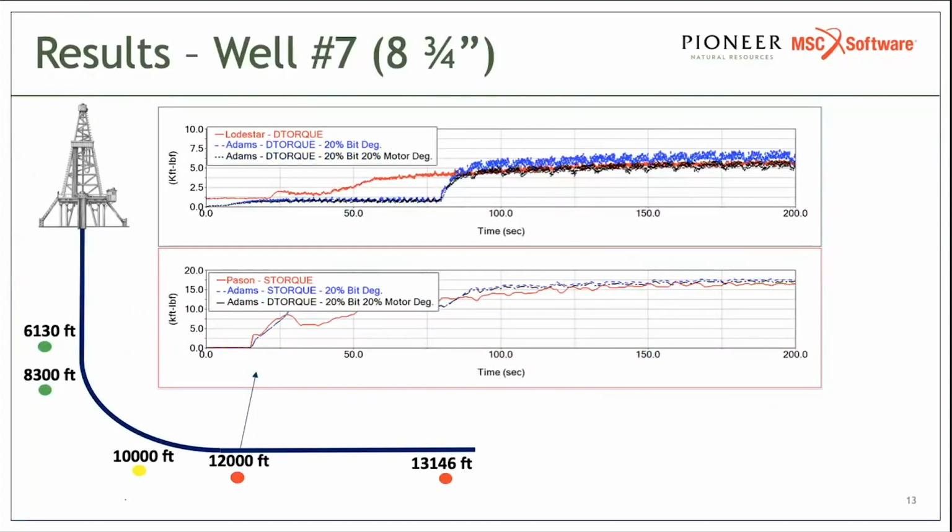We have the planned hole data. So the drilling engineer gives you the planned trajectory, and you can use that as the initial start point and just model the whole file using that. Later on, when you get survey data, you can go back in and update the whole file using survey data.